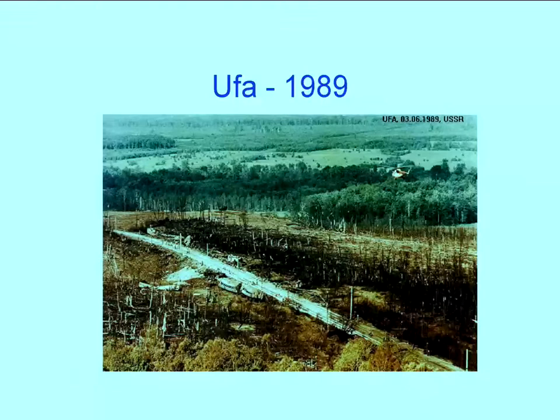The other significant learning point was that the operator was under pressure to keep this pipeline operating. It was a very long pipeline, and it was feeding some sort of industrial process at the other end. And the operator was having trouble keeping the pressure up, so they kept increasing the pressure. And of course, the reason they were having problems keeping the pressure up was it was leaking, which is a mistake which is quite common and easy to see how it gets made when the operators are very remote from the location of the pipeline.